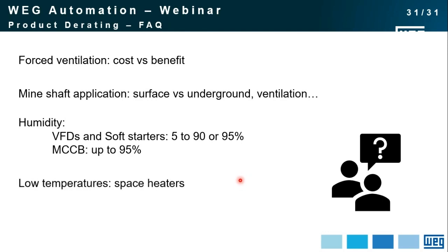And that can lead to another harsh environment, which is low temperature. I haven't said much about low temperature, but that can be solved once again by using space heaters. Before using your application, you have to warm up your panel so your components can operate correctly. And in conjunction of humidity and low temperature, not only water but even ice can be found in your panels. So you have to make sure that you first melt down the ice and then you start your panel.